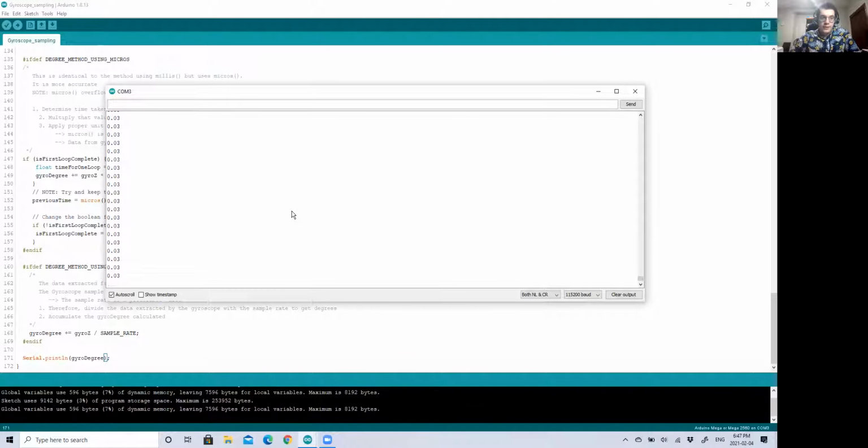If you really want to, you can remove the error that is produced over a certain amount of time. So you can use a counter, and after, let's say, 1,000 inputs of the counter, then you can just remove, let's say, 0.05 of the gyro degree. Or you can even create a digital filter, which just means if the gyro Z, which is the input extracted from the data here, you can just allow some variables to update and some not. However, I would recommend that you just keep it as it is because the error is quite insignificant.